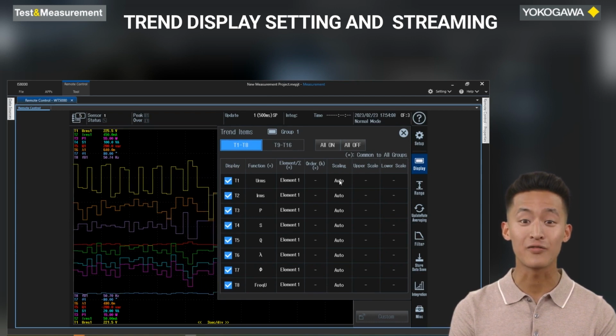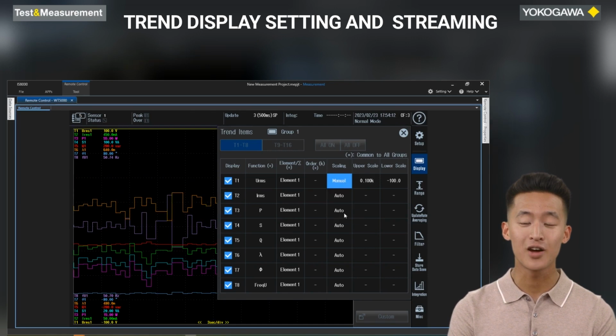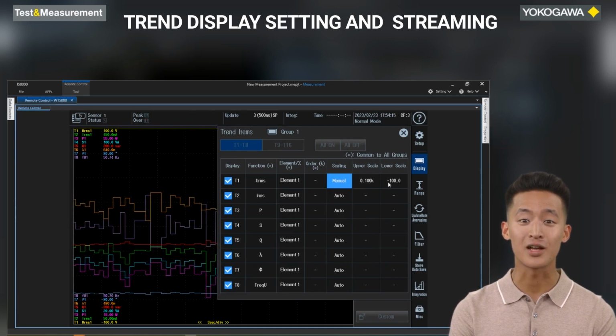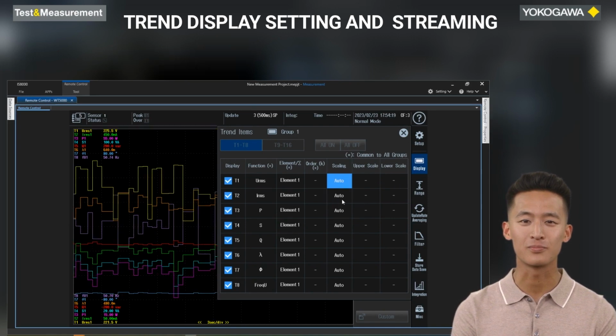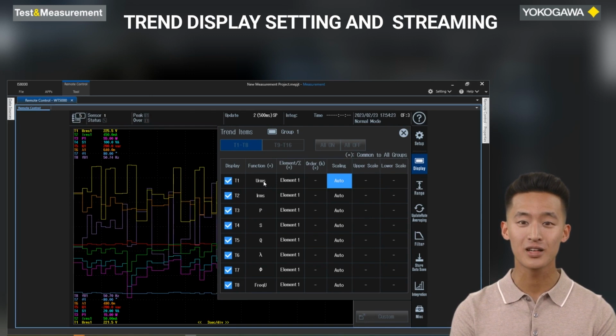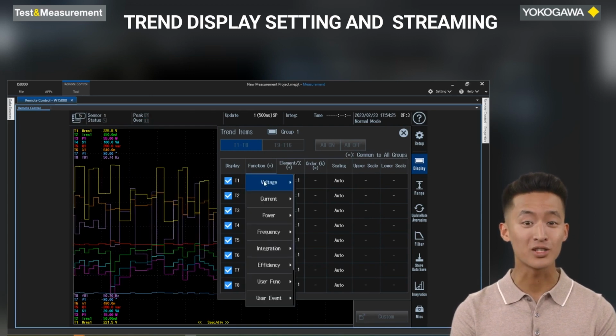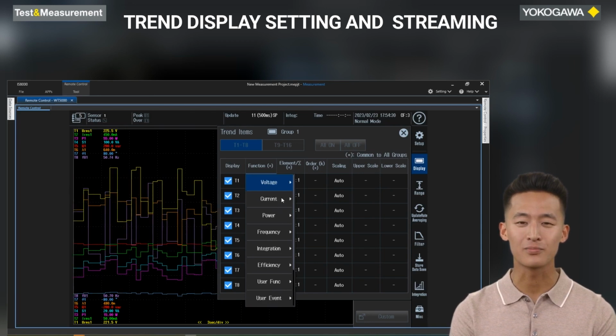Scaling of the trend graph can be either auto or manual. In manual, user can define the range of scaling. In this measurement, let's use auto mode. We can allocate any of the parameters of any of the element to a particular required trace with the flexibility of configuration in WT5000.